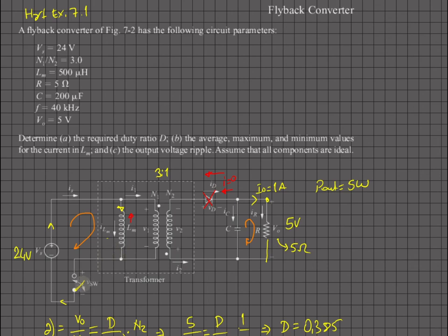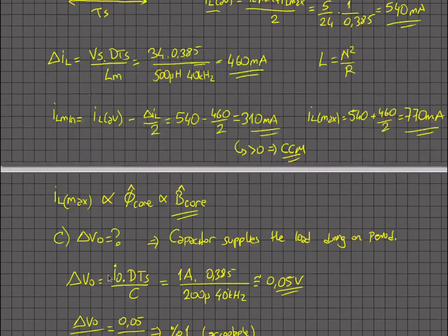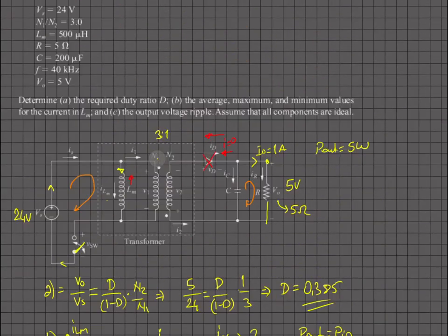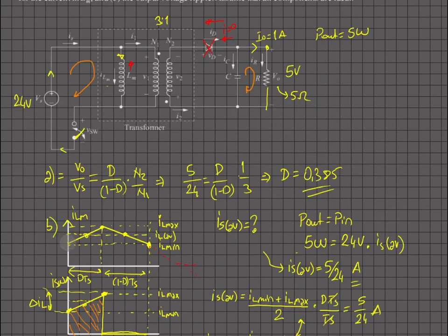Secondly, when you are turning on and off your transistor, if it were continuous conduction mode, you would be turning on your switch while the inductor current is at that level, or turning off your switch when the transformer or LM current is at that point. So you will have increased switching losses.